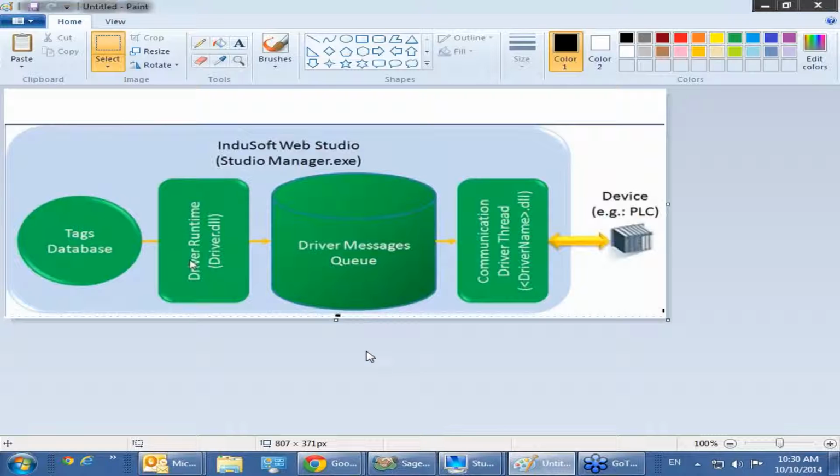Okay, so he's asking in particular about ZigBee slave mode. There are different kinds of application modes, like addressable mode, which is an advanced mode where you only transmit data to specific ZigBee slaves from the host. Because, for example, if you had a really large application where there were a lot of ZigBee modules, you may not want to transmit the data out to every module in the network.